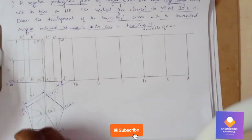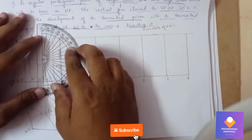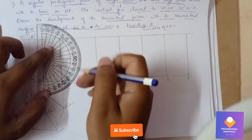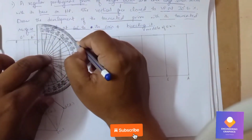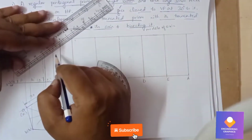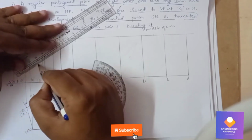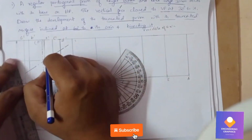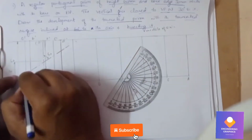So now here in this question, the axis will have an inclination of 60 degree, that is the truncated surface. From that axis we need to consider an angle of 60 degree. So this is a tricky question. From that axis point, the truncated surface, we need to consider an angle of 60. So a little bit different. You can show the angle from the axis to the truncated surface. That's the angle here.